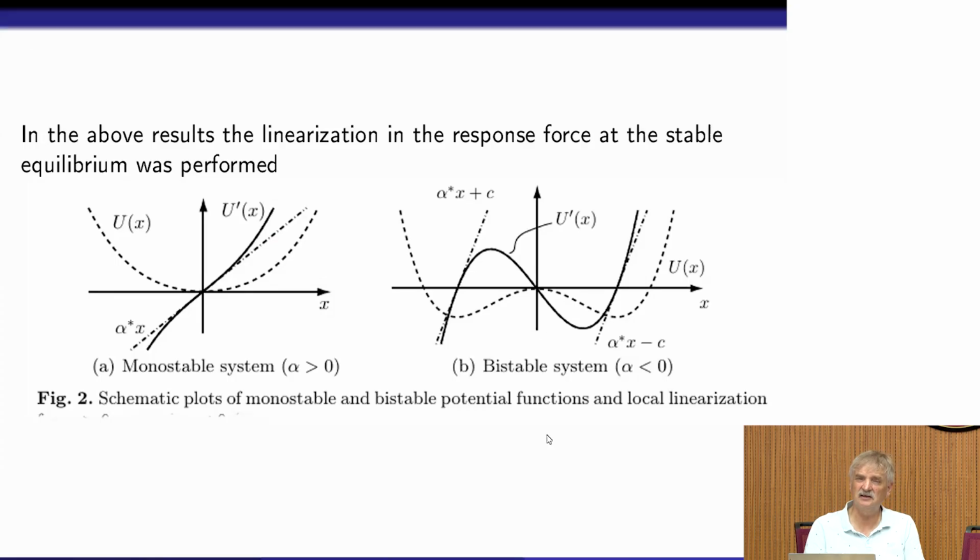On the left-hand side you already have a minimum, like a single potential well, so this is quite easy. You see that the force is not linear, because if you follow the full line, it would be some hardening, maybe hardening in this case. But in the vicinity of the equilibrium, it is a good fit.